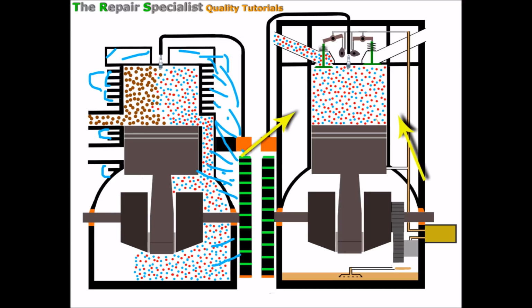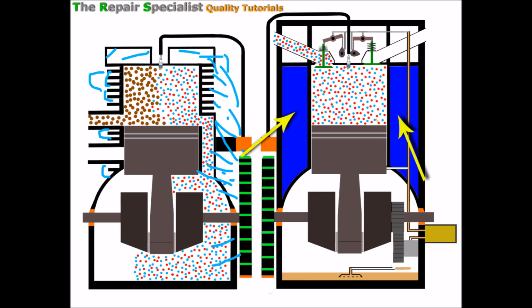And that's where these areas come in as important on the 4-stroke, because they are hollow cutouts between the cylinder and the outside environment where the water is pumped through. So cool water's pumped through these areas and it cools the engine down as it's pumped through. And this system, of course, has its own water pump and radiator and fan to keep all this water cool and allow it to circulate through the engine. And as that cool water circulates through the engine, it takes away from the engine a lot of that heat, allowing the engine to keep cool. And when I say circulating through the engine, I don't mean through the actual engine itself into the cylinder. As you can see there, it's in a special compartmentalized area there, so it can't get into the engine itself.